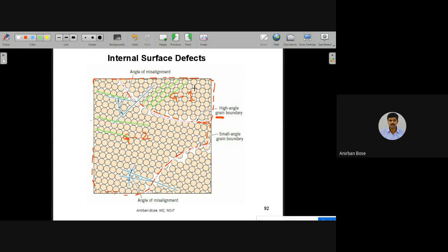So this is basically grain 1. This is basically a crystal. If they have a similar identical structure, that we know is called a crystal structure. This is a crystal, and this is again another crystal. So here grain 1 and grain 2 are basically crystal 1 and crystal 2. When they are meeting in a material, you can see this is a polycrystalline material where different crystals are there, and within a particular crystal they have the regular feature, but they have different orientations if you observe.